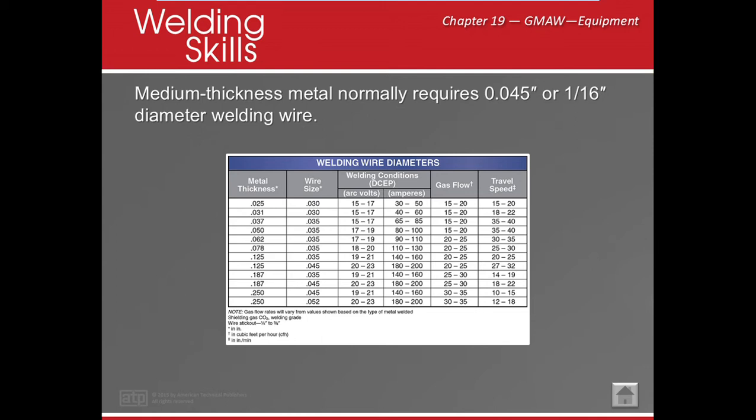So, I digress. Let's look at the slide. Tell me how we're going to choose the diameter of your wire or electrode. You guessed it, thickness of material. For now, let's look at 1/4 inch. GMAW comes in sizes from, remember this is on a test, 0.023 inches all the way up to 1/16 of an inch. This chart kind of ballparks thicknesses, diameters, volts, and amperages for you to use. It's not a, hey, you have to use this. This gives you an idea of what you can run at.